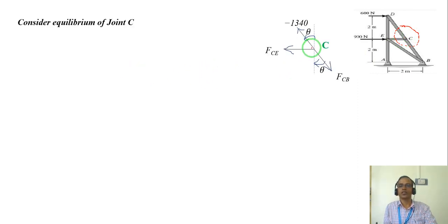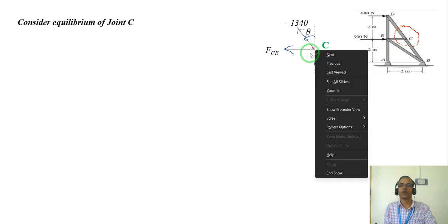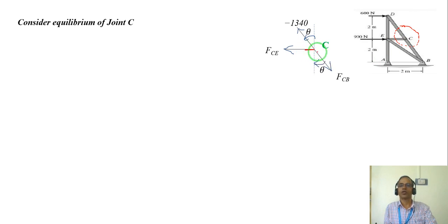So what we do is simply make a line around the joint and cut it off from the joint, and you will see joint C like this. So this is joint C. This member is horizontal, this is inclined, and both will have the same inclination. And whatever the angle is, if I draw a vertical line here, whatever angle this is, it must be this, right?